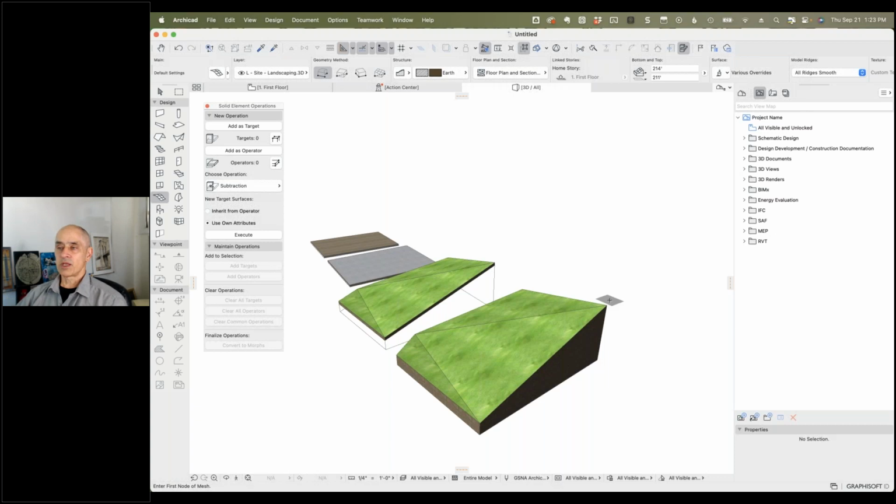So it used to be that you had to download the goodies one at a time. There are about a dozen of them, give or take, to install them. One of my favorites is called the Poly Count. It counts up the polygons on individual elements or the whole model, which can help you to optimize for complexity, make sure that certain things are not using too many polygons and slowing you down. Now, most recently, the goodies are installed as a whole. You just do one download and it installs all of them.